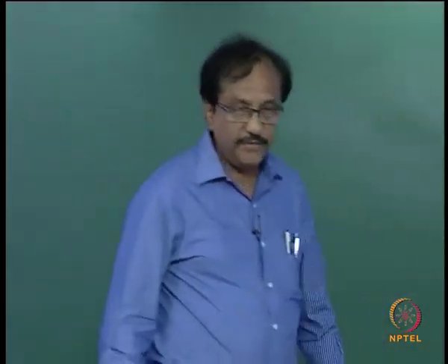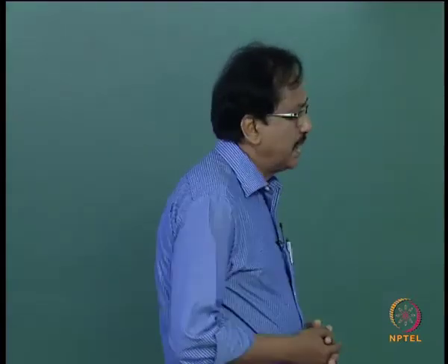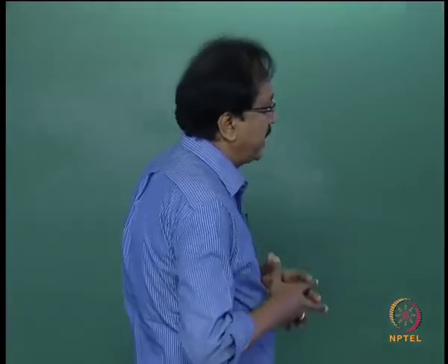But one thing you should be very careful about is determining the distance between the shoreline and the breakwater, the length of the breakwater, and the gap between the breakwaters. All these things are going to depend on the geomorphology of the coast and the wave climate, like the wave height, wave period, as well as the direction.